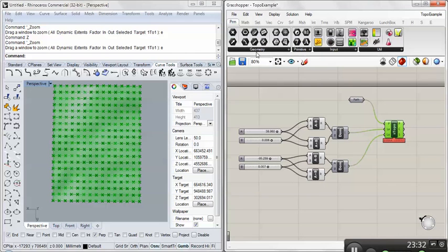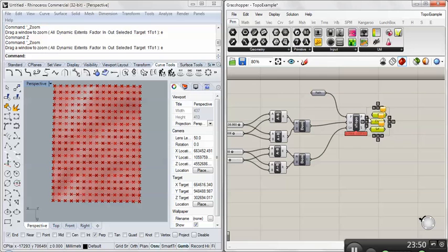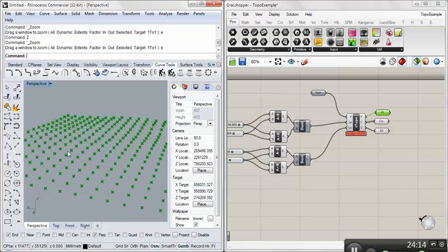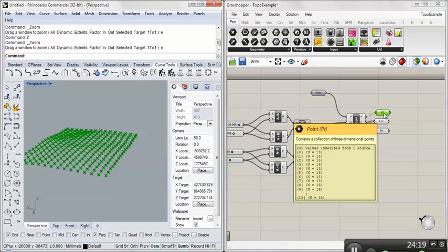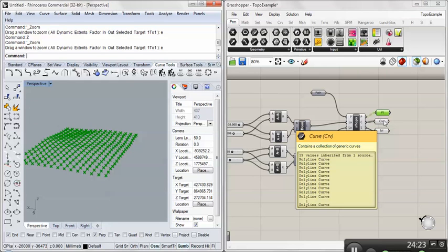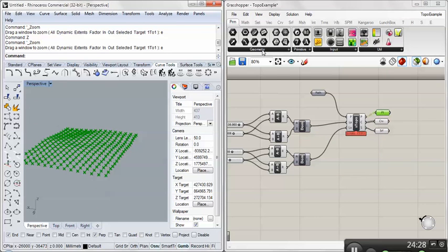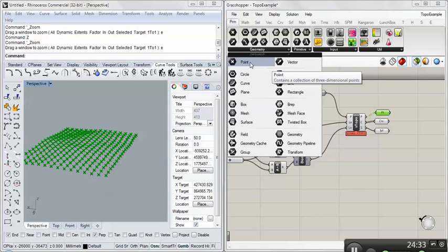So I'm going to grab 3 boxes from params so we can separate those out. You want a point box, a curve, and a surface. Go ahead and drag each item to that. If you switch to preview mode, which is the green, so only items selected, you can look at each data set by itself. What were the 3 things you used? Point, curve, which looks like that, and surface, which is that. They're all under the geometry box of the params tab.